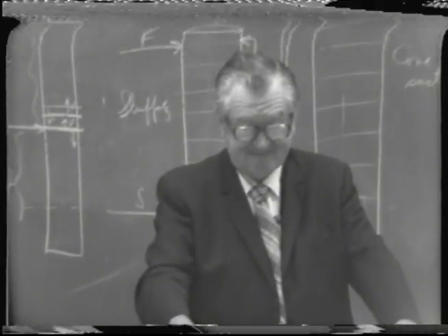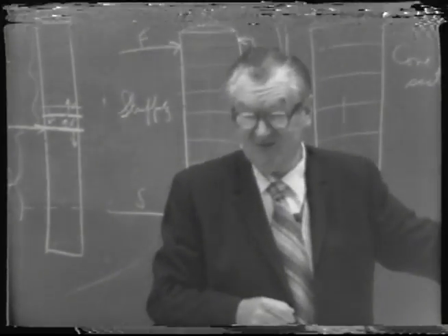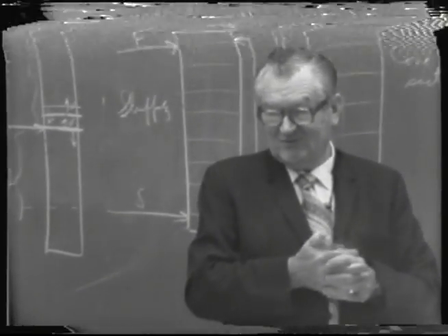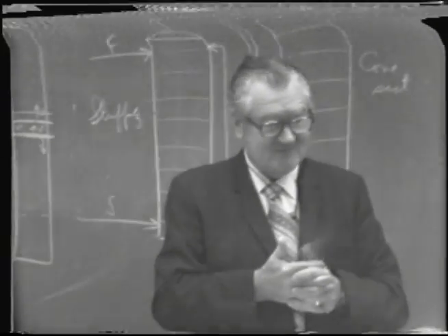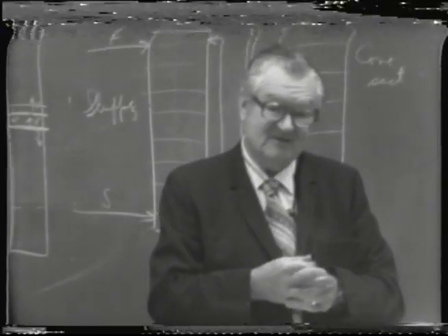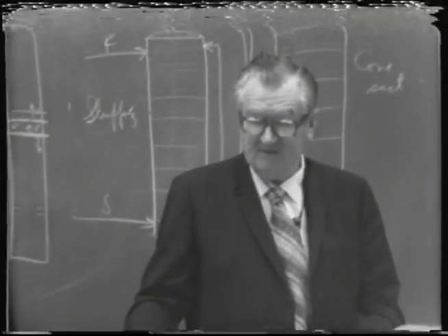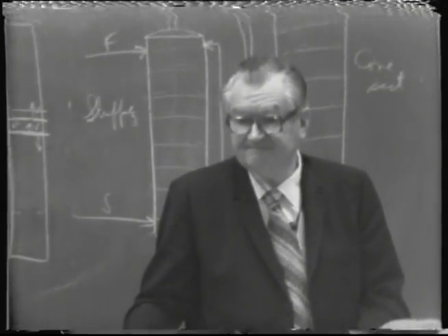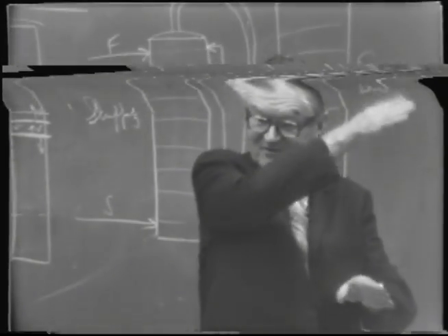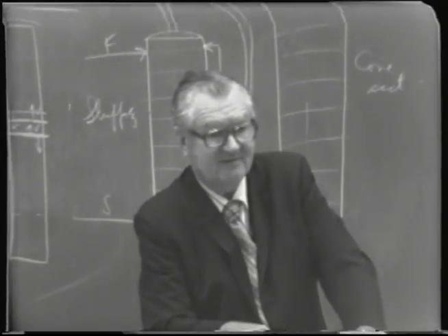And so by getting the dilution low enough, by adding water to the column, the so-called extractive distillation principle, you can cause almost all organic flavor materials, or contaminating materials if you want to look at them that way, to be made more volatile than ethyl alcohol. Remember that chart I gave you, a volatility chart, where if you get them low enough, they cross over the alcohol curve.